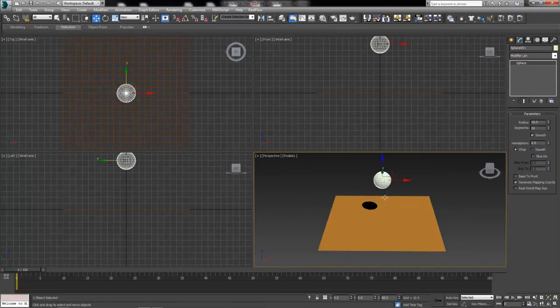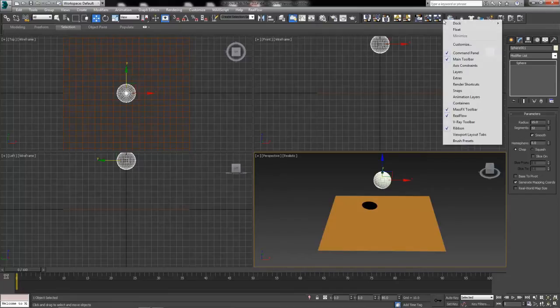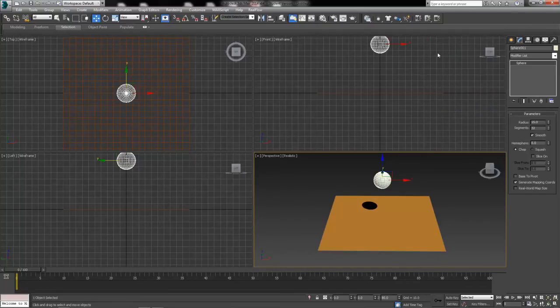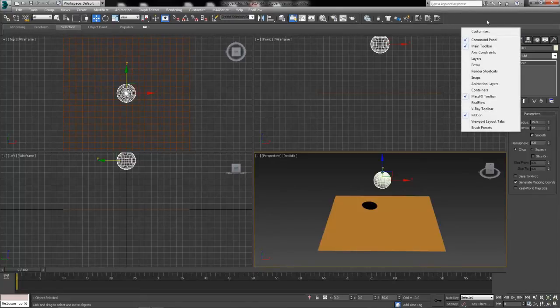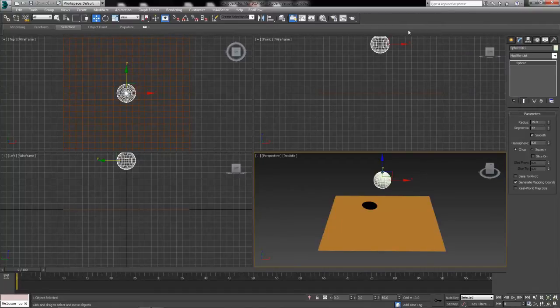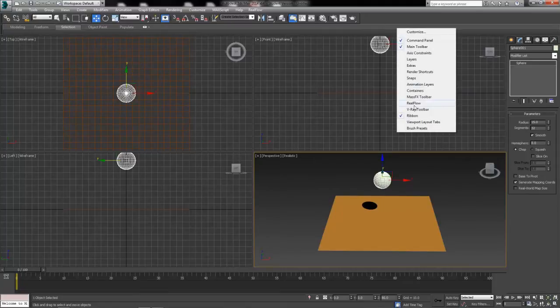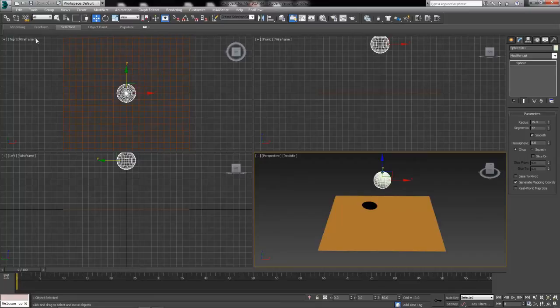We can go ahead and set up the rigid body here, which is just our sphere. It's fairly easy, and the rigid body dynamics are in another tutorial anyway. We do that by coming up to our menu up here. I might have a menu or two that you don't have. And if you don't see this one, the one with the sphere and the t-shirt and a little stick figure guy and the playback buttons on gears, more than likely you'll need to right click out here in the empty space and make sure your MassFX Toolbar is checkmarked. Without it, your standard package looks like this, and then you'll turn it on and it'll either show up here or floating over here, and you can drag and drop it to here.